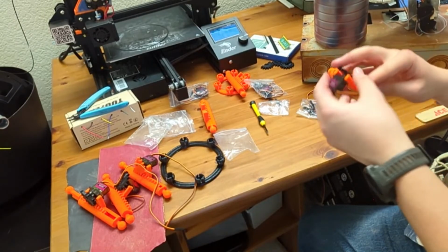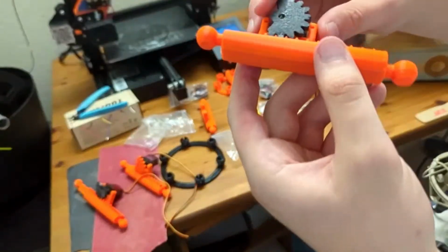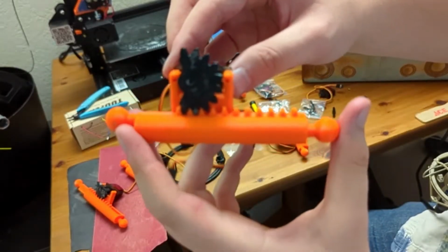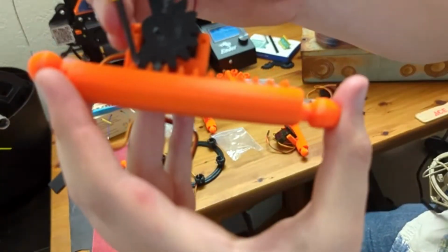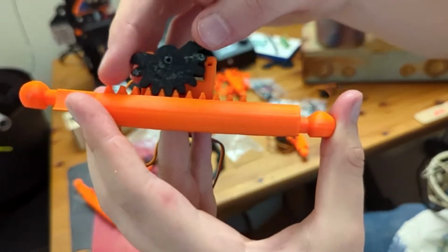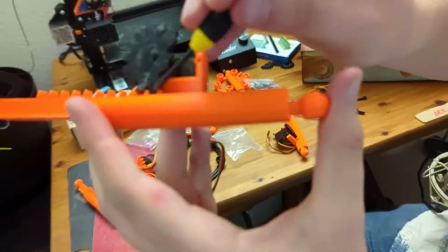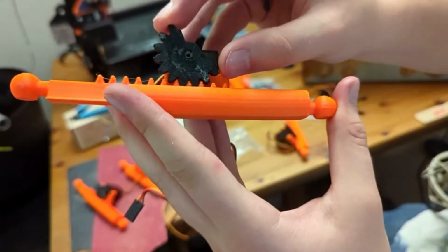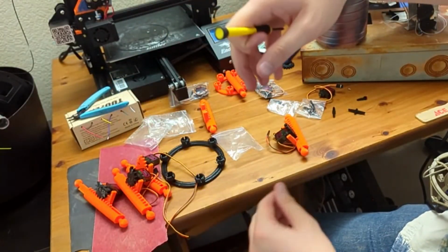I designed these actuators. So if we look at this one, I designed it so that the gear teeth, the pinion teeth, mesh exactly with the rack teeth. So you can see I got it so there's one tooth beyond the end of this pinion gear. And if we go all the other way, there's one tooth at the end of this rack gear before the servo reaches its limits. And I did that so it's super easy to assemble, as well as minimizing the actual space of the actuator.